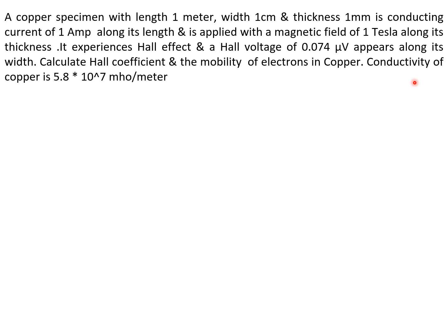It experiences Hall effect and a Hall voltage of 0.074 microvolts appears along its width. Calculate Hall coefficient and mobility of electrons in copper. Conductivity of copper is given as 5.8 into 10 raised to 7 mho per meter.